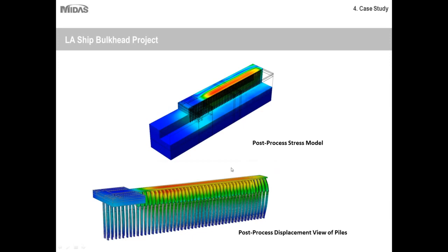And upon the finished analysis, the client found that the projected preliminary study was safe for construction. So with the piles improving the current ground conditions, they began to see if they could reduce the number of piles while maintaining the safety factor. So this was something that I had mentioned earlier about numerical modeling, is that it's very handy for design. For example, as I said, in this project, they found that their initial design met the safety factor requirements. Afterwards, they started to see if they could use maybe fewer piles while still maintaining that minimum safety requirement. That way they could not only maintain safety, but also cut costs to work more effectively to create more optimized designs.